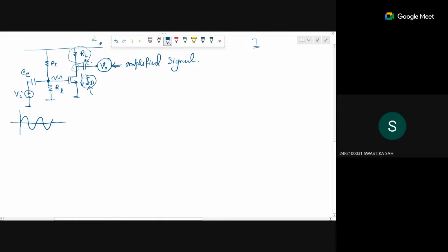That's okay. Why is the capacitor used? To remove the DC part. So to remove the DC part also, we are using that. And generally, these small signal things are small incremental signals that are changing. The signals are incremental. Incremental means that it is constantly changing, or changing from a particular point.